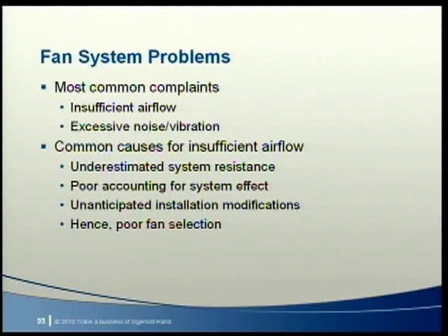It usually results from either a poor estimate of duct system resistance or failure to account for system effect at the air handler connections. It's hard to predict from a drawing how a duct system will actually work after it's installed, but duct sizing programs can do a pretty good job at this.